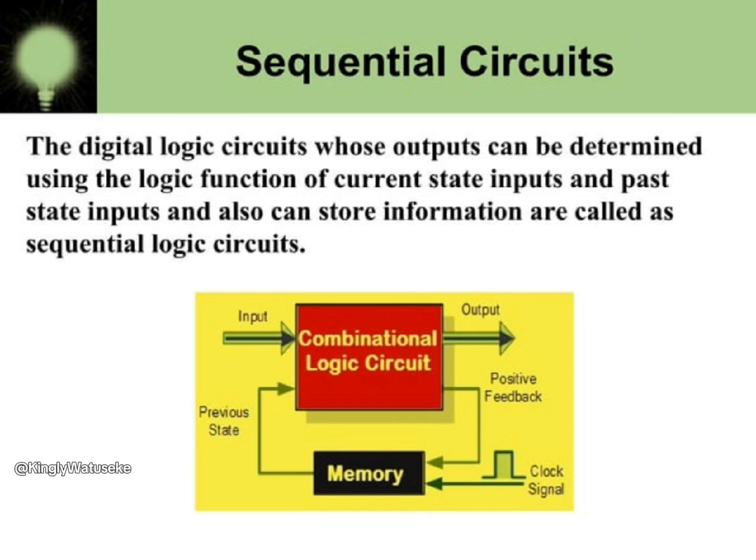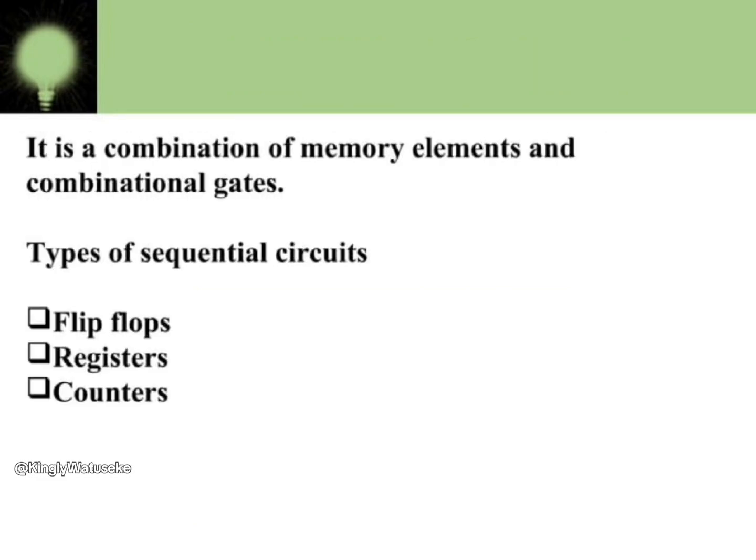Sequential circuits. The digital logic circuits whose outputs can be determined using the logic function of current state inputs and past state inputs, and which can also store information, are called sequential logic circuits. It is a combination of memory elements and combinational gates. Types of sequential circuits: flip-flops, registers, counters,